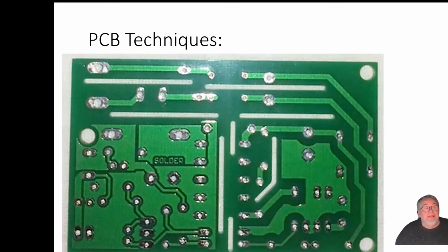There's slots to keep the mains wires away from each other and away from the low voltage stuff. You'll notice there's pads for putting in the varistor, but that's a whole other story. And then at the bottom, because it's a switch mode supply, it'll have a high frequency transformer, and that high frequency transformer will be prone to arcing as well. So there's a series of slots with the primary side of the high voltage transformer, which is on the right of the board, and the secondary side of the high voltage transformer on the left, with